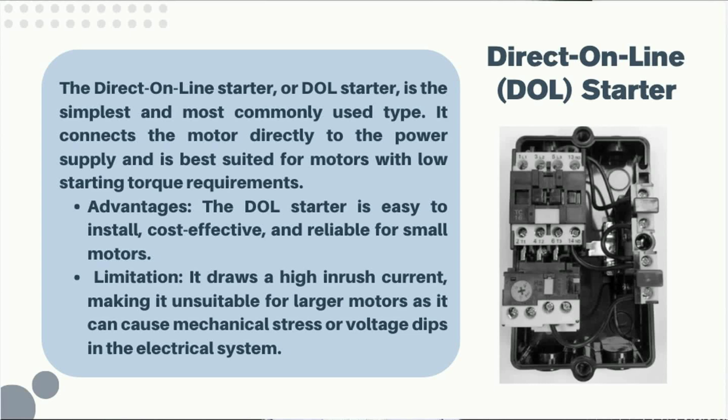Types of starters. Now let us look at the three main types of starters commonly used in electrical systems. Each type is designed for specific motor requirements depending on factors such as torque and capacity. Direct online starter. The direct online starter, or DOL starter, is the simplest and most commonly used type. It connects the motor directly to the power supply and is best suited for motors with low starting torque requirements.